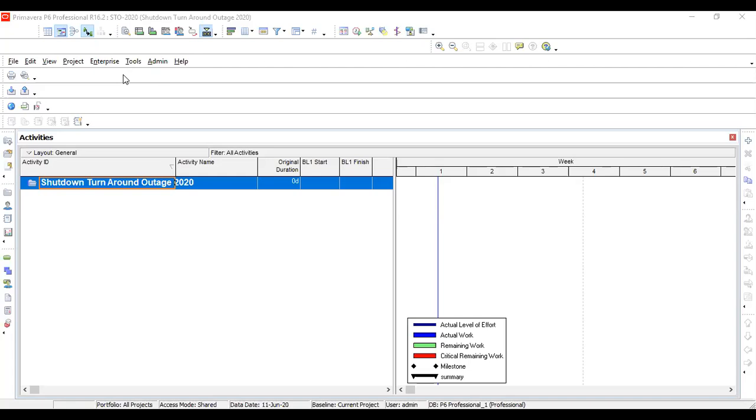So this time I need a WBS window over here, because remember one thing: every time you start with Primavera 6 after developing a new project file, you have to go for your basic settings like industry selection, and then before getting into Primavera's project planning, you have to develop your WBS. Because right now, stick with this concept that we are in the planning phase, we are doing scope management, and we have to understand how to do that scope management on Primavera 6 with the help of WBS.